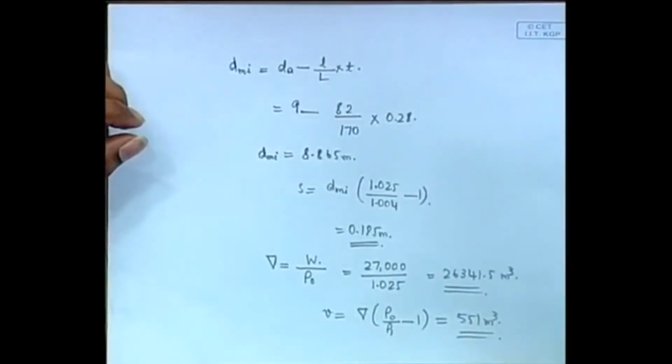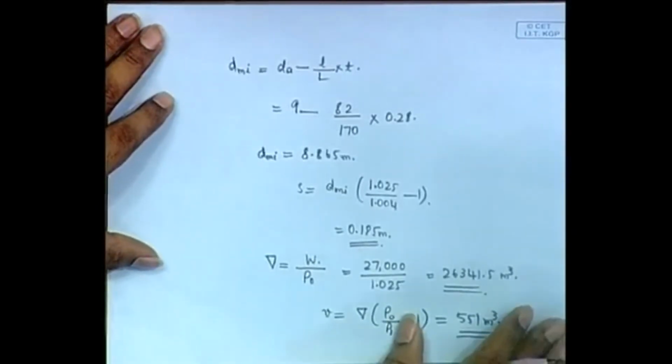Now this is the parallel sinkage. Now there will be trimming. That is the next thing you have to calculate. Whenever there is a load added or a change of density, the two cases are exactly the same. The only difference is that in case of load added, the moment changing trim is equal to W into the shift in the center of gravity, G0 G1, the distance through which the center of gravity shifts, and that will give you the moment changing trim.